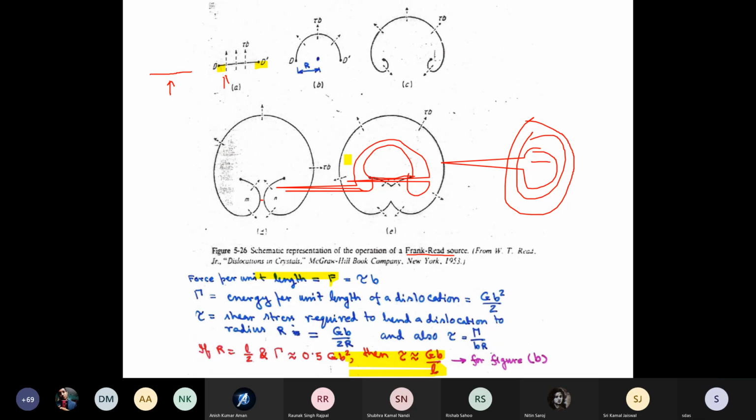The reason? These are heat treated and very fine precipitates are there. Now if you want to weld it, the temperature is very high. You are melting a portion of it and rejoining it. So these fine precipitates, with the heat, will become very large in size. So L will be very big.